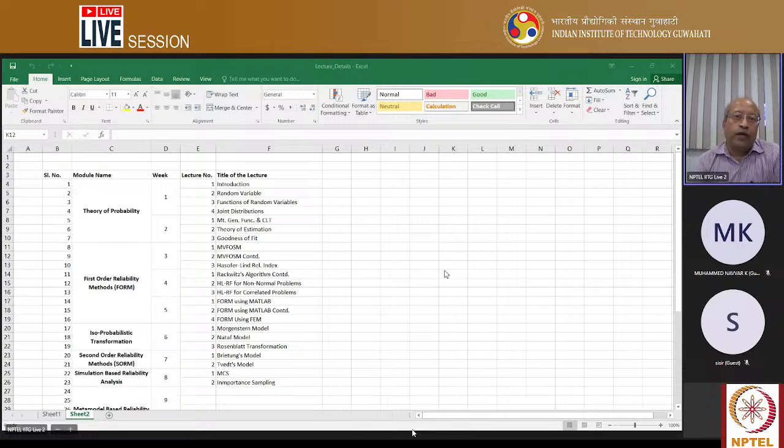And the way we combine the first order reliability method, the way I showed you, is exactly the same whether you use APDL or Workbench. At the end of the day, you have to get that .inp file, and then using that .inp file, you can do the reliability analysis. So any problem you solve in finite element, you can combine with the reliability. In fact, in ANSYS, most likely they have an optimization toolbox also, if I'm not wrong. So there also you can go for some level of optimization in structural analysis. That also you can combine with our model, the way we solve it. So I hope that clears your doubt. If you have anything more, please ask.